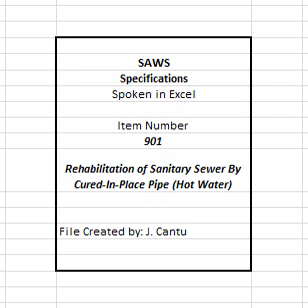F. Protect the liner and components during all phases of work including, but not limited to hauling, installation, entry into the entry pit, and prevention of scarring or gouging of the liner, pipe, or components. G. Contractor will be responsible for monitoring weather prior to planning a CIPP tube insertion to account for a sufficient duration of tube wet out and insertion and curing in order to ensure that wet weather that will prevent access to the project site is accounted for.